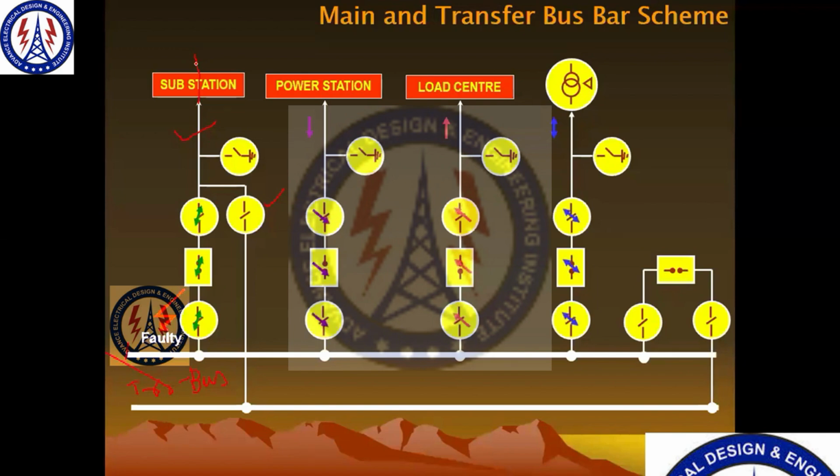Okay, so in that case we adopt such busbar scheme in which we are giving priority to the feeder supply. Correct. So here when we have the fault on this feeder, we are giving priority, and in this case, this feeder again runs. You just close this circuit breaker, and the power from here will go this way and will go this way.